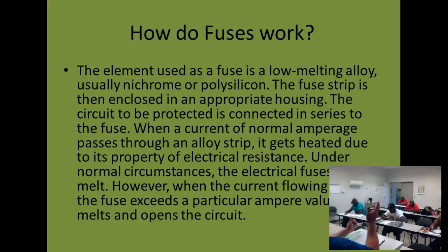Well, that fuse blows. Boom. That's no good. So I have to have a fuse that's 50 or 60 amps. That's never going to show up when there's a problem with the compressor. Now it's pulling 30 amps when it's running and it's not starting. We've got a problem. So they're saying use time delay fuses if you're going to use fuses, or breakers, because breakers will allow that for a small amount of time.